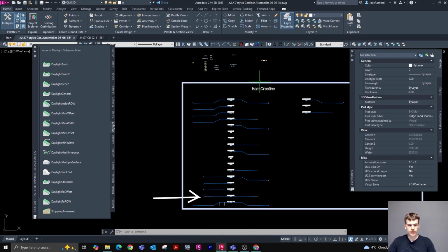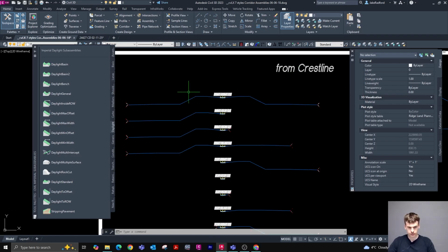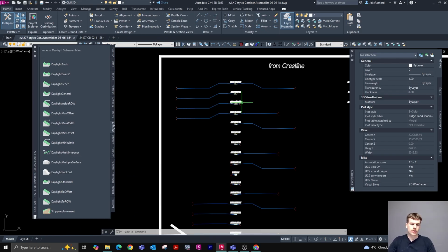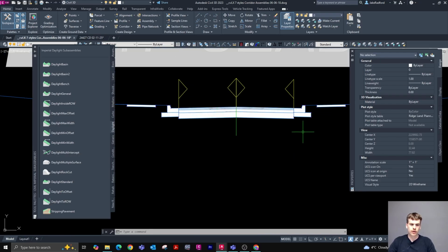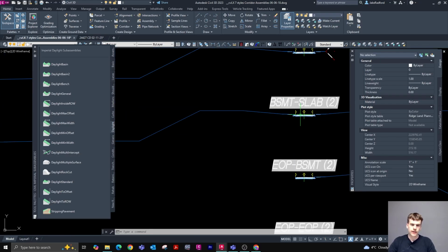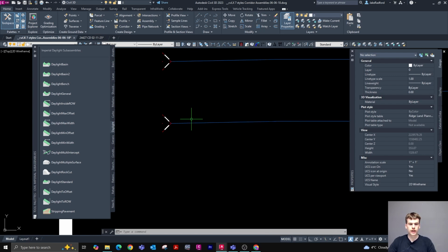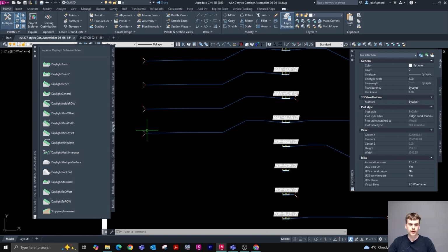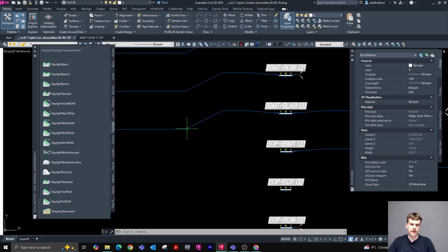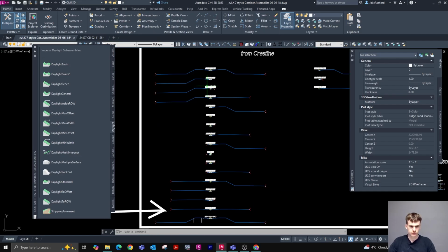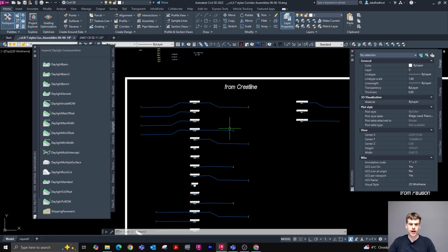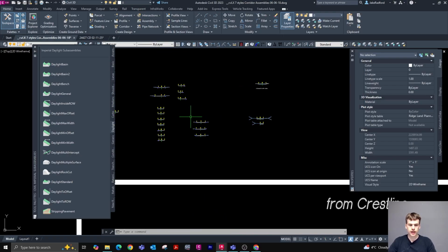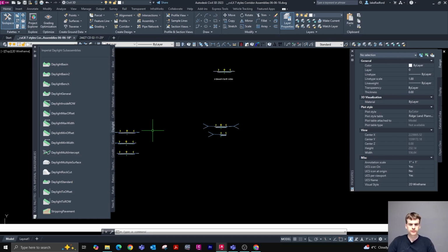These ones under this From Crestline box are used to do pretty large swaths of site grading. So you have a road here in the middle with sidewalks on each side, and then it'll grade out a basement lot for you, which will then daylight after the specified widths of the basement lot and specified slopes and whatnot. So you can do some pretty large corridors that are going to do a lot of your grading for you. However, that gets quite complex, and we'll probably touch on that a little bit more later.